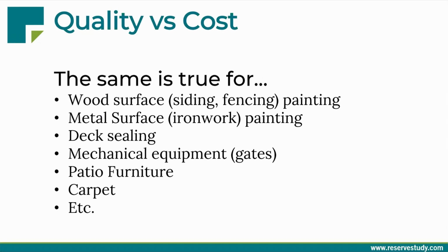Your wood and metal surfaces on the exteriors are very vulnerable to weather elements. So the repainting and resealing of the exteriors is crucial to prevent high repair costs, to extend the useful life of siding, which is critical. Decking sealing prevents water intrusion that can cause structural damage. So ignoring a $1,000 per deck resealing project could result in a $10,000 or $20,000 per deck reconstruction.